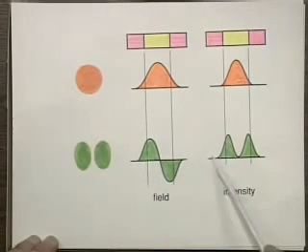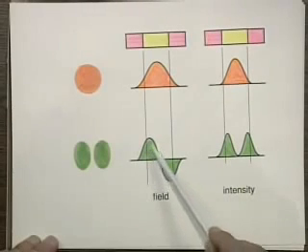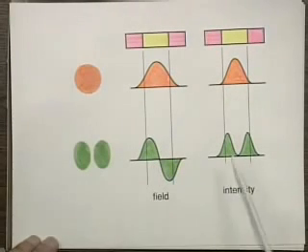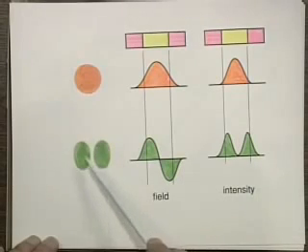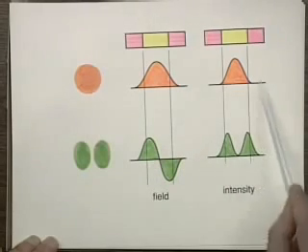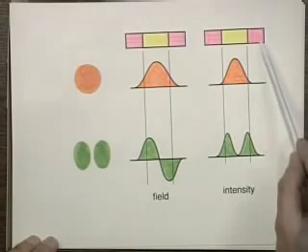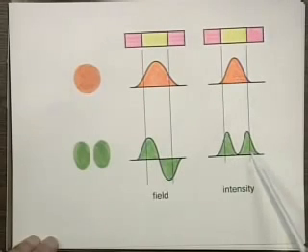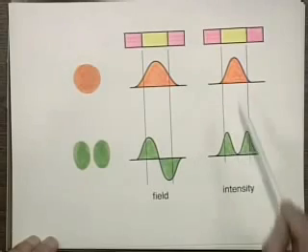And when you square it up, if we look at the intensity, it looks like this. That's what these two spots look like. But the field is really, one is, let's say, positive, the other one is negative. And what you see here is that the size of this higher order mode is bigger than the lowest order mode, and more of it will propagate in the cladding than in the core. So in terms of propagation constant, or how fast they propagate, this one propagates more in the cladding than this one, and since the index is smaller in the cladding than in the core, this one will go faster than this one.